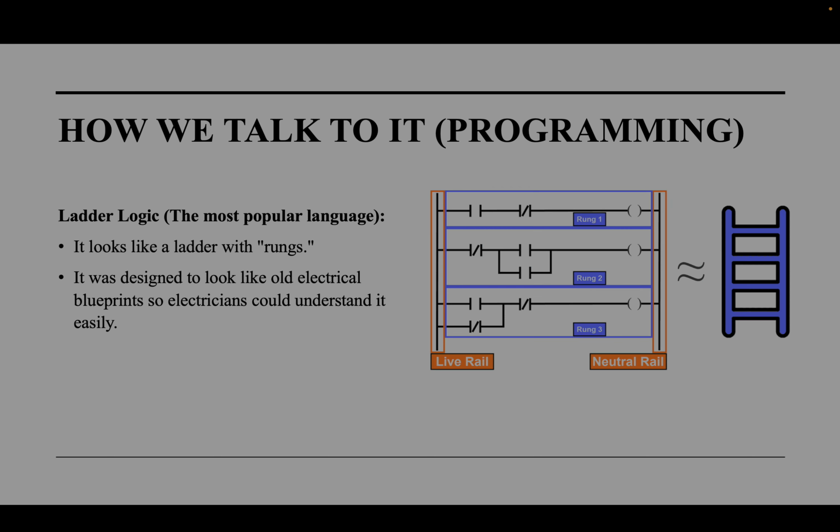Now I'm going to talk about ladder logic. We program them using ladder logic. It looks like a ladder with rungs. It was designed this way so that electricians could understand it easily, as it looks just like old electrical blueprints they were already used to.